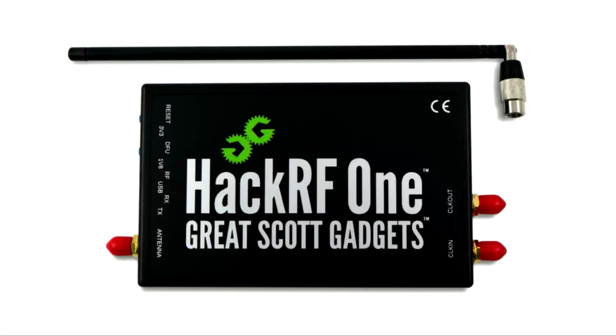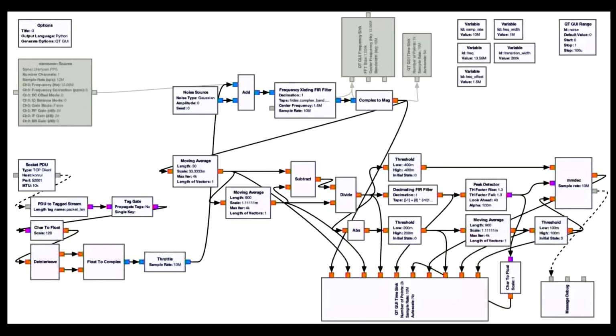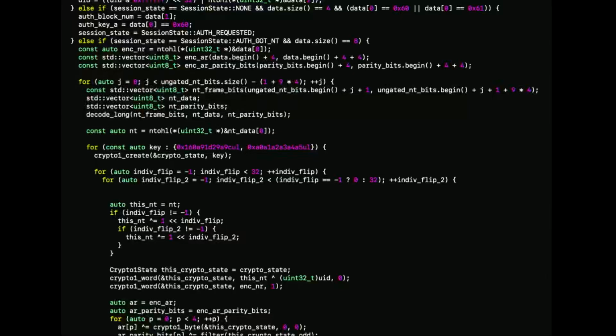So using HackRF, that's a software-defined radio, and GNU Radio, which is a software-defined radio framework, we can make an unholy mess again. But what this does is basically read in data from the software-defined radio antenna, do a bunch of pre-processing, and then put it into a custom written block. What this custom written block does is look at only the bare minimum amount of messages that we care about just to get a valid Cardax access credential.